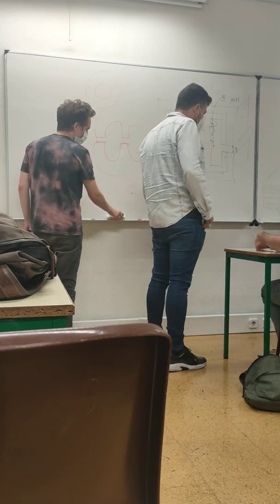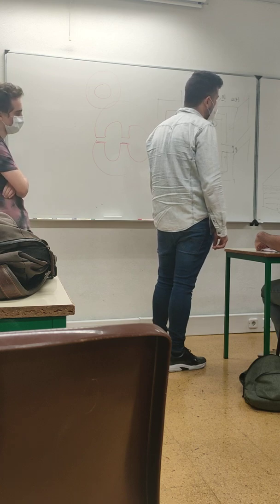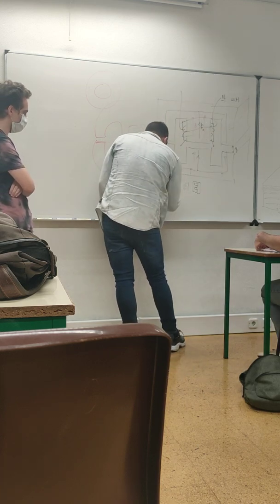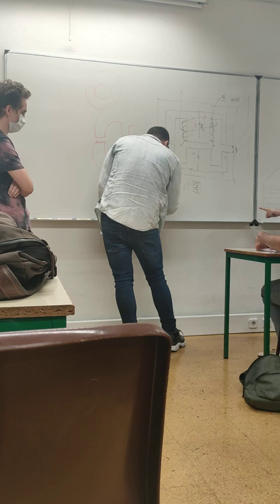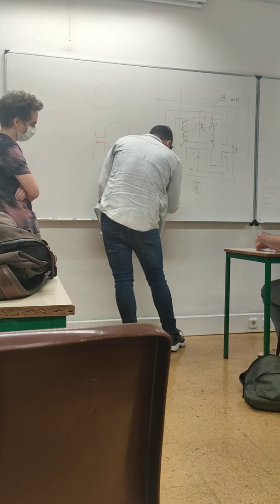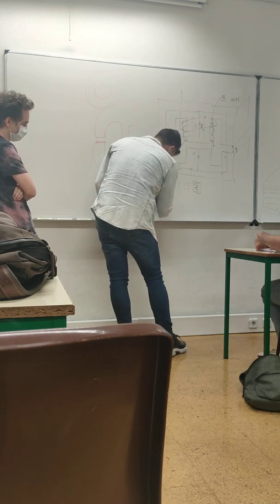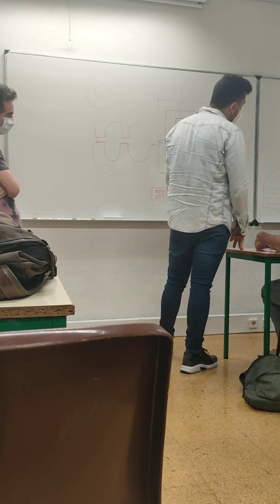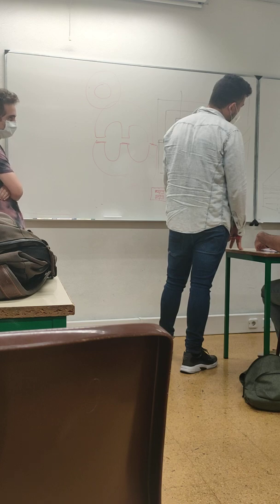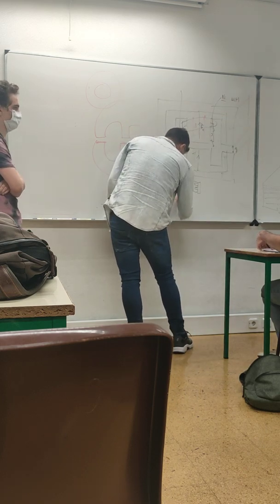That's why I put this in 3D. This is one lamination. You have the varnish, and you have another lamination here, like a sandwich. So the machine is made and cut, like your colleague has told, for the flux coming from here, walking in this direction. If we put the flux in the wrong way, what do you see here? You see still air. It is air from the magnetic point of view, because you have varnish.